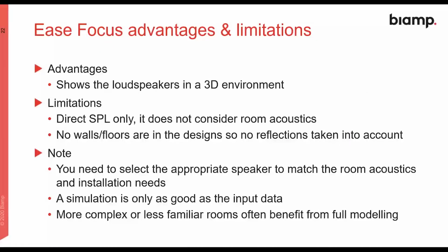Advantages, it shows you the loudspeakers in a 3D environment. Limitations are direct SPL only still in the software. It does not consider room acoustics or the walls and floor finishes, so no reflections are taken into account. If you do need software to look at the room acoustics and reflections from walls and floors and the different surfaces you can use, that's where you need to go to the next piece of software, which is the full Ease Standard software.